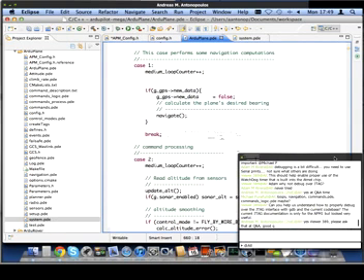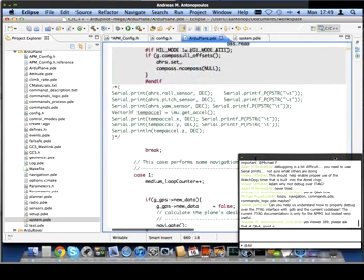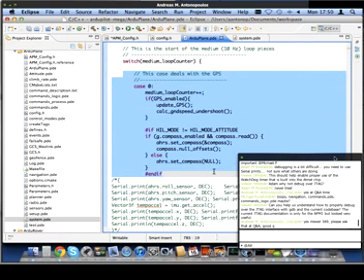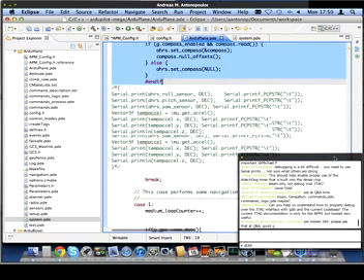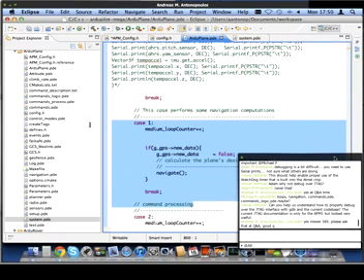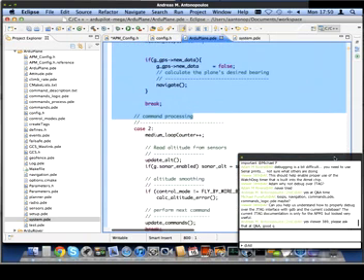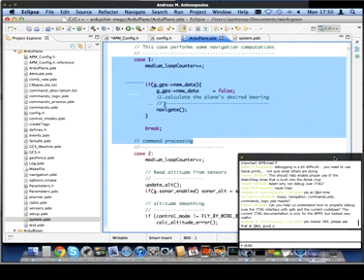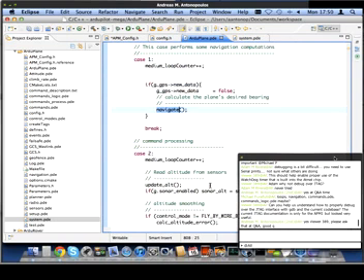So the first time you call medium loop, it's got this little medium loop counter. The first time you call it, the counter is 0, and it does the case 0 case. And when that is 0, then what it does is a 10 hertz calls. So all of the stuff within that case 0 is called at 10 hertz. Then all the stuff with case 1 is also called at 10 hertz. So this gives us a breakdown from 50 hertz down to 10 hertz operations.